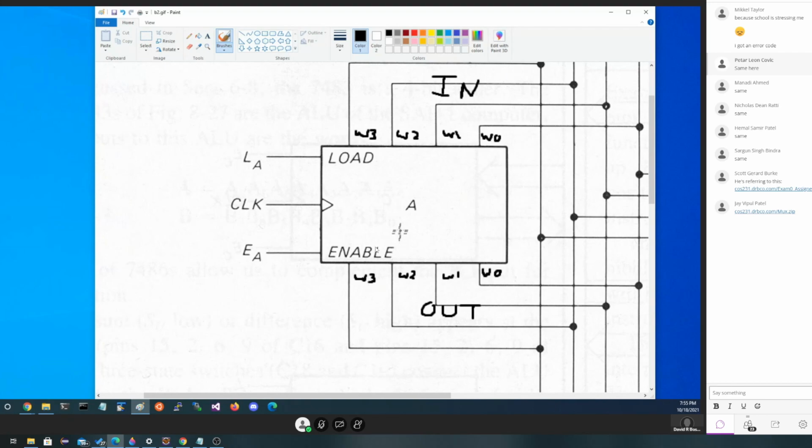Now, because we're calling these boxes bus type registers, meaning they can read and write by way of a bus, we have to have some control signals which allow us to say, are we reading or writing right now, or neither one? So if we want to read, we need to assert 2 signals. Load and the clock signal will be used.